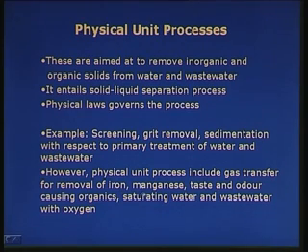Removal of iron, removal of manganese, manganese also should be removed. Manganese also can be removed by the aeration and precipitation and sedimentation, and then we can also use aeration for the taste and odor causing organics. To remove the taste and odor causing organics, we can use gas transfer. Taste and odor causing organics are generally volatile in nature.